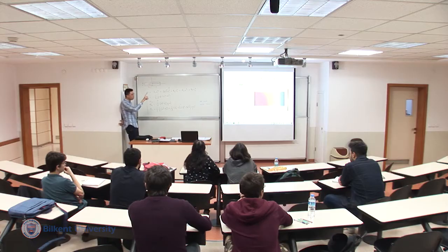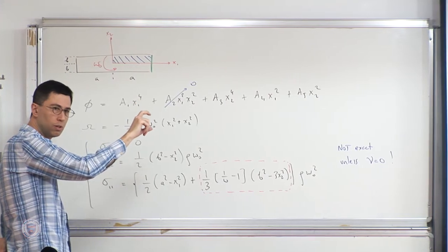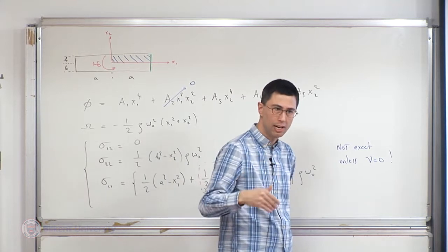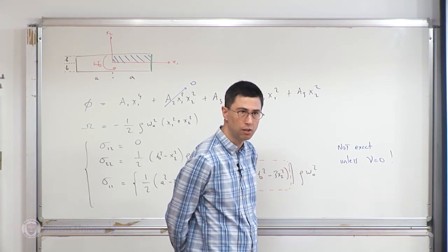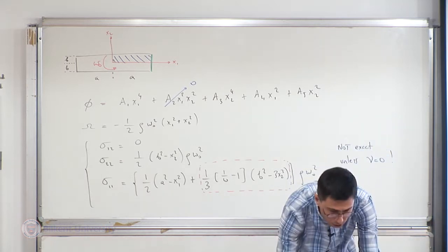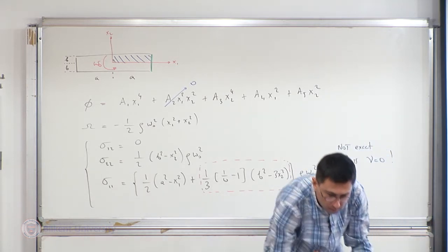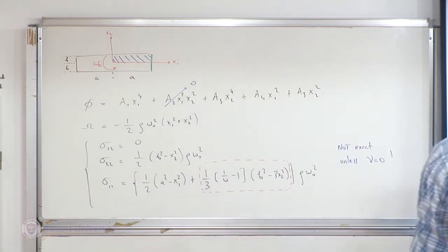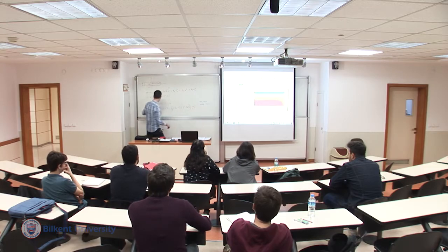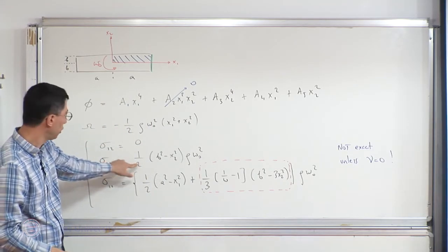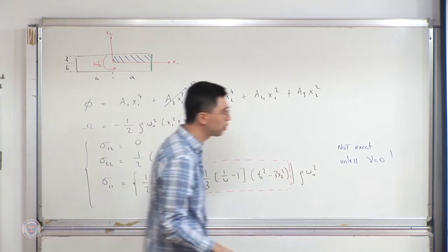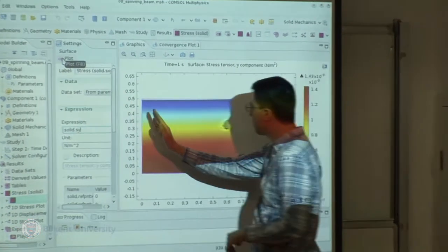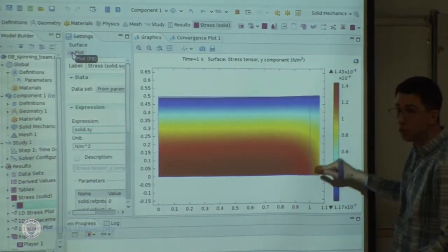Now, eventually, what we will observe is that as the height becomes much smaller than the width, the shear stresses will be much less than the normal stresses. Okay, so let's look also at sigma y. Order of magnitude-wise, at this stage, it is similar to sigma 11. And now, have a look here. This is my prediction. I predict only a variation along the 2 direction, but obviously, variation along only the 2 direction is a picture that works rather well here, but not in this region.